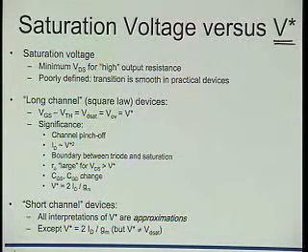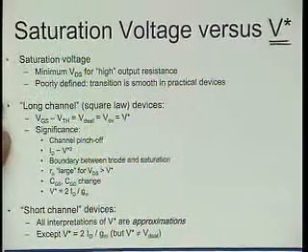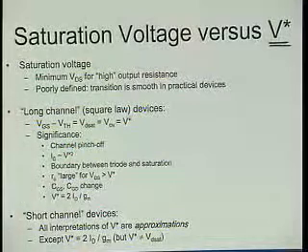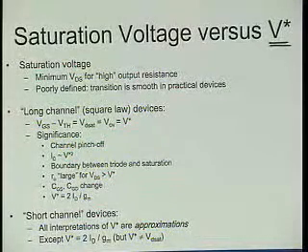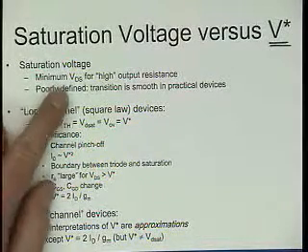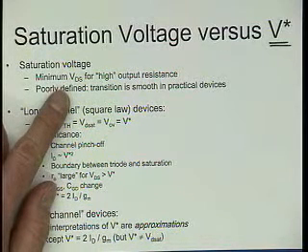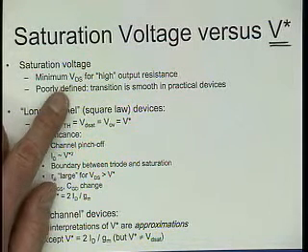And the confusion really is that VDsat is extremely poorly defined. It has a ton of meanings, and none of them is extremely well defined. One of them is that it's the minimum VDS that I need so that I suddenly and miraculously get high output impedance. Well, we've seen that minimum just plain doesn't exist, so speak of a poor definition, right?